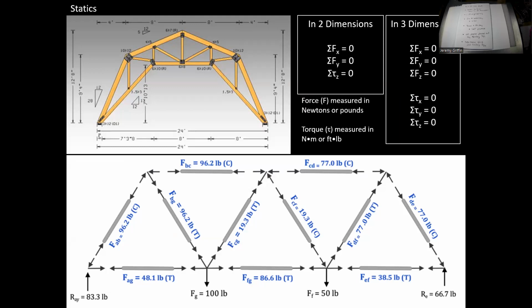Right? But by the way, one project I want to have you guys do before spring break is to build a toothpick bridge. So give a good look at this, because this might give you some ideas about how you can optimally design a toothpick bridge, right? Where, you know, if you've got support on both ends, and you got a huge weight in the middle, which is how we're going to run this. That whole top end is going to go into compression, and then the whole bottom is going to go into tension. So start thinking about this.